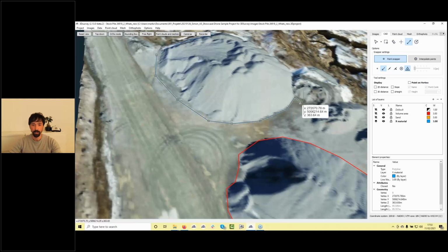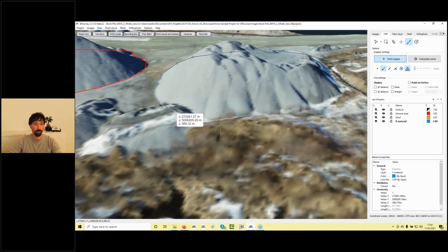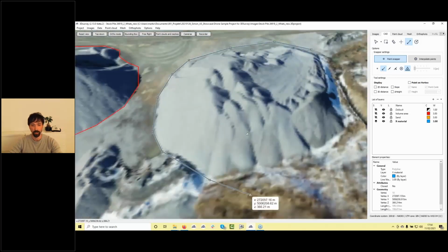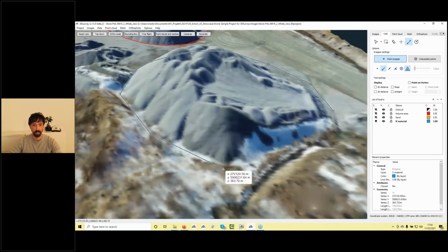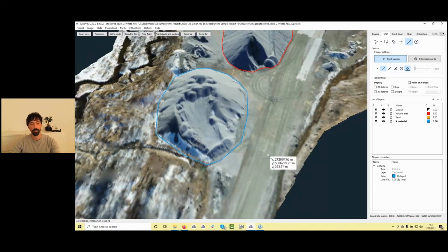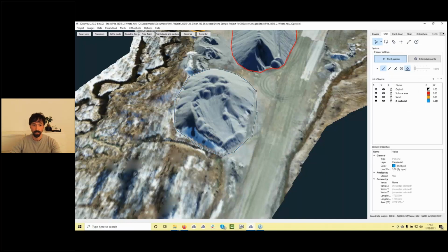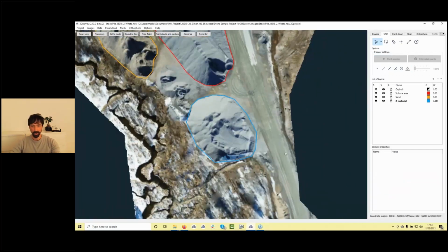What's the benefit also here? Here you can actually rotate and zoom in during the selection also. So this is another benefit in comparison to calculating the volume with the selection option. At the end, what's important, I need to close my polygon line. Okay, so how can I check this? If I go to the select tool and select my closed polygon, here it's written closed, yes. If this line is not closed, the volume is not going to be selected.